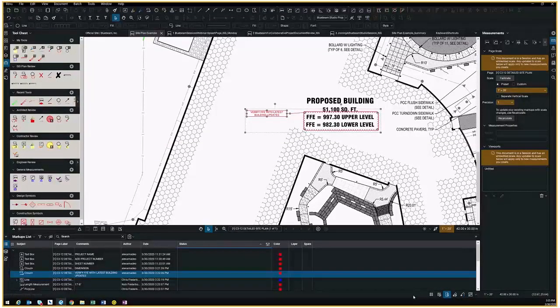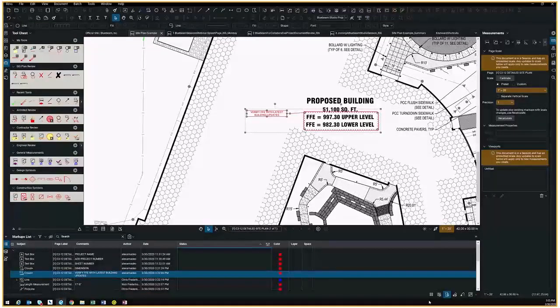It's F8, if you were wondering. So F8 will turn the status menu on and off for you. The status menu allows you to put a grid on to snap to. It allows you to put gridded lines on, and do a number of other things. So snap to is one of them that's used quite regularly.